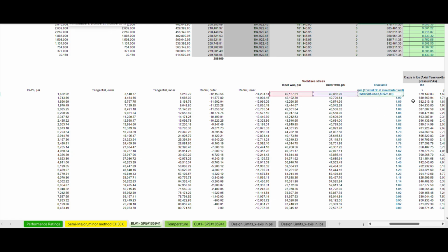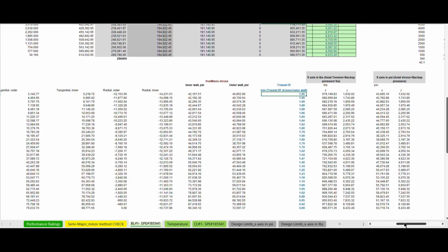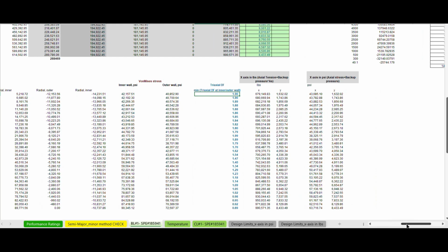which is calculated here. I divided them into the yield strength, so you take the conservative approach there. As I mentioned, I didn't do temperature derating on the yield strength in this example. And I used the nominal wall thickness. Here I put these two columns to be able to plot them onto our triaxial ellipse solution for the burst ellipse and